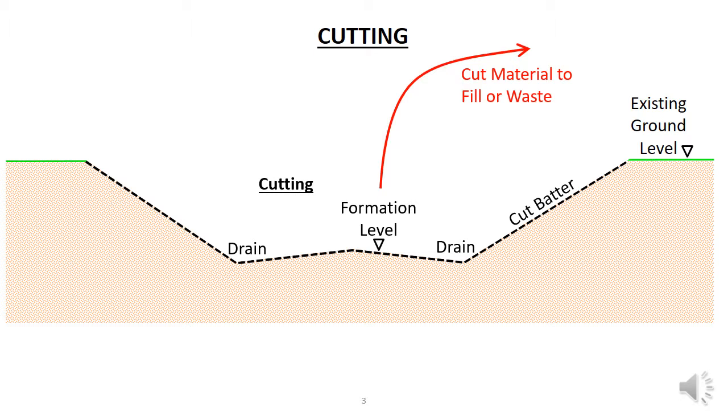They need to be cut at a slope that will remain stable over time. Weathering can change the chemical composition of the soil, which can weaken it and destabilize the slope. The slope will also become saturated by rain, and the additional weight of the water in the slope soils can also destabilize it. Erosion by rain and wind can also remove material off the slope and may also result in the whole slope becoming unstable.